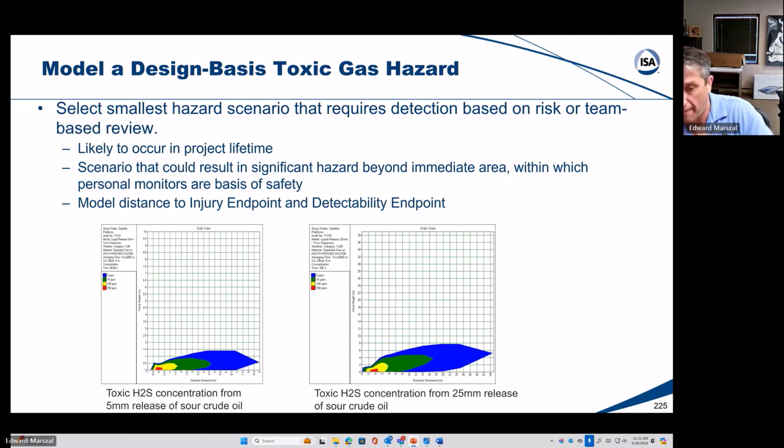Then in the actual site installation, the location may not be exactly the same as what we proposed in the fire and gas detection mapping. So we'd like to get advice from you, whether let's say a difference of 5 meters from the proposed location, is it considered acceptable without doing any mapping?